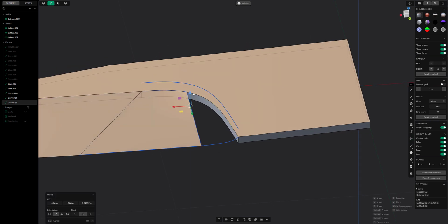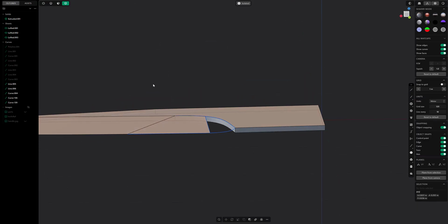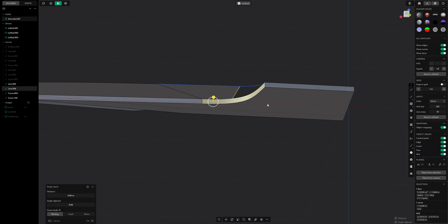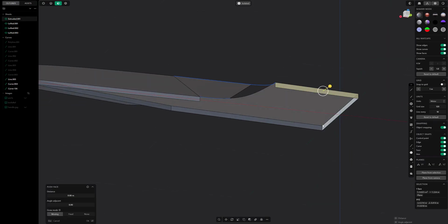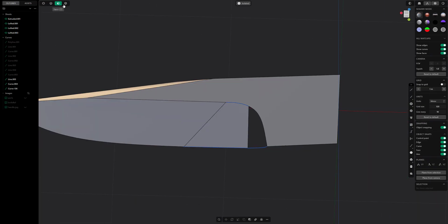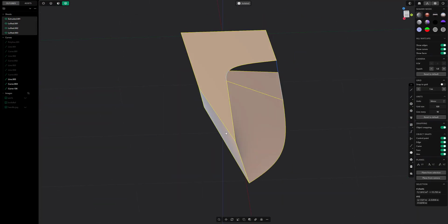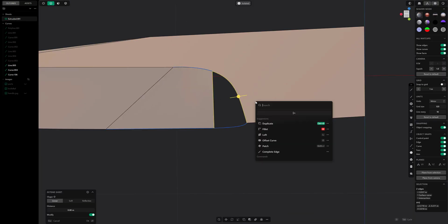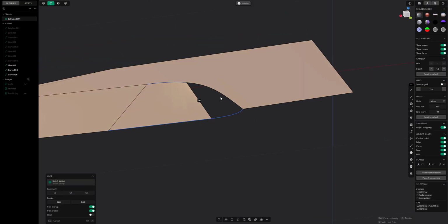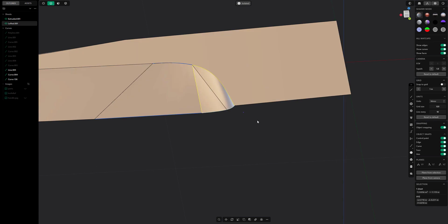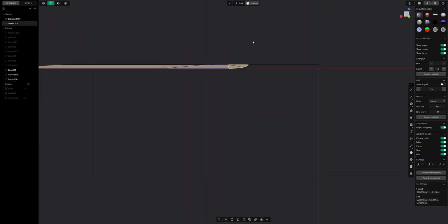There's a few different ways I could do this again. One, I could copy the edge and trim it, or I could combine those sheets with the main body. So here, deleting the thickness so we don't have anything getting in the way, and taking these and joining them together with J. So now I should be able to loft these together, and it looks like it's pretty good. Not the best transition there, but it's good enough to continue.